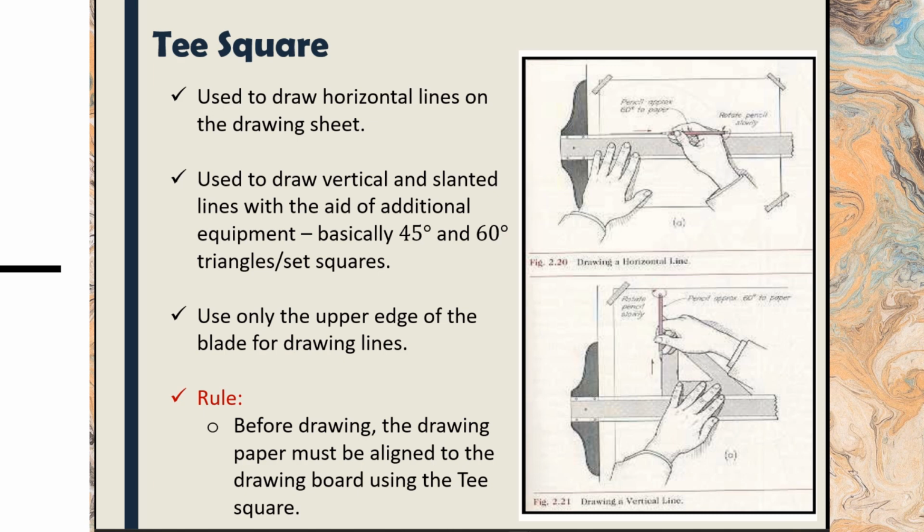That is why your T square must be in good functional shape. The T has to be a T, and ensure that the T head is not shaking and is aligned perfectly well with the left hand side of your drawing board. I would like to mention at this point that you take adequate care to protect the left hand side of your drawing board. Especially when not in use, be sure not to put that edge on the floor, or you can protect that edge with a cardboard or a paper that will adequately keep it smooth and prevent it from getting rough.